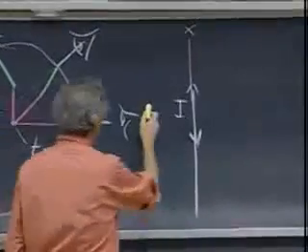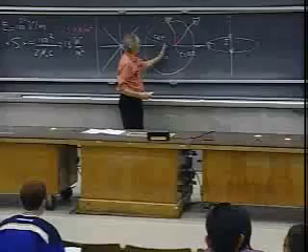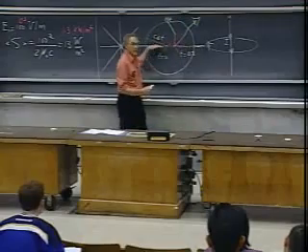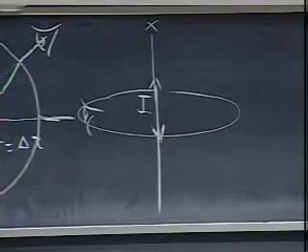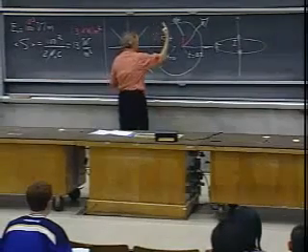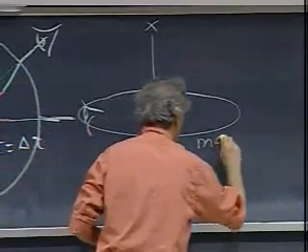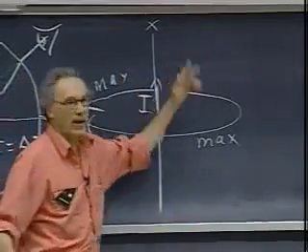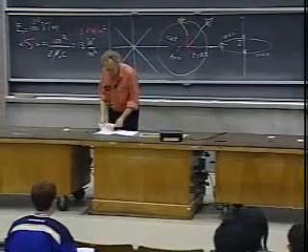But we also know that in the direction perpendicular to the acceleration, that is in this direction, remember here the acceleration was like so, and in the direction of the acceleration, no electromagnetic waves go out. So nothing goes out here, nothing goes out there. But in the plane perpendicular to A, which in this case of the blackboard is a whole plane like this, and in this case of the antenna is the horizontal plane, here we have a maximum radiation going out. Everywhere in this plane. And in between, somewhere, it's not zero and it is not the maximum value.